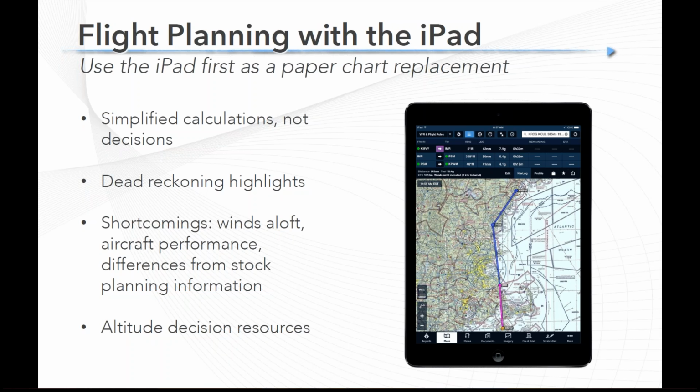It will help you tremendously, but it's going to simplify the calculation, not the decision that you have to make based upon that information. It's going to give you information, not insight, is kind of how I tell it to most of my students. So don't expect that just because you plug in a flight plan to your iPad that suddenly it's going to tell you how to get there. Yeah, it's got a course, a chart and a number, but it's not going to have all the rest of the information you need. The iPads, depending on which app you have, the dead reckoning, which is the big piece in terms of time, fuel, distance, those are just tremendous.